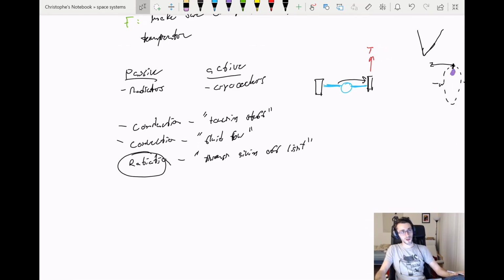So places where you'd want to use a cryocooler would be something whose temperature must actively be maintained and controlled. This isn't typical for onboard systems, which have at least a marginal tolerance range for their temperature. They don't care about being a specific temperature, they just want to stay within a range.